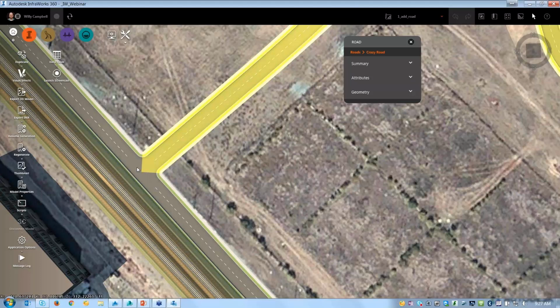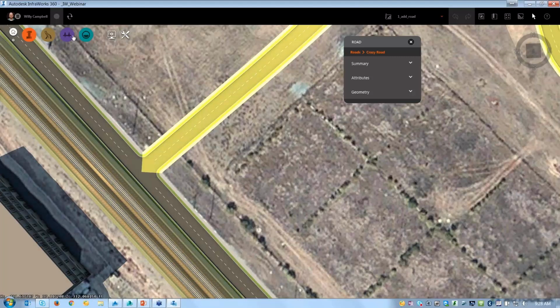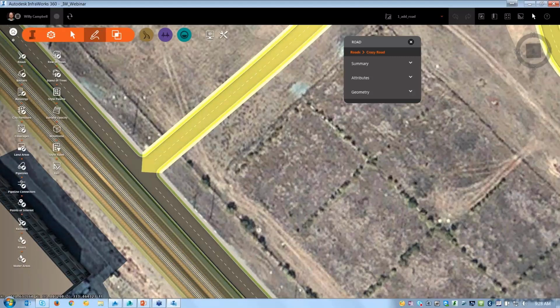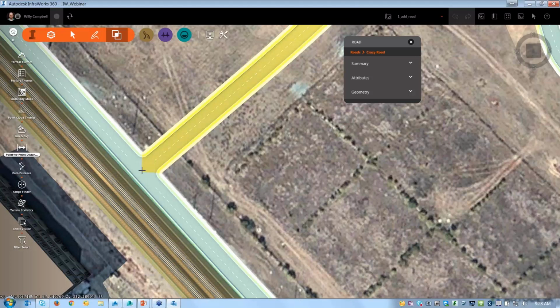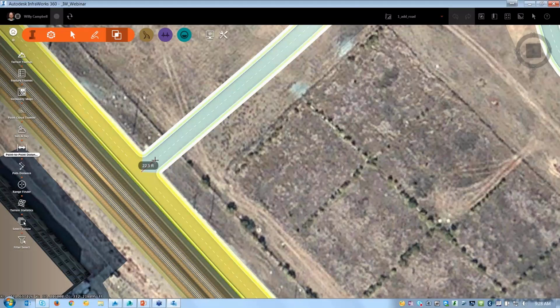So what I actually want to do in Civil 3D before I export my line, and I did manage to forget this step again, but we can do it real quick. Let's see how much distance I need to trim back from this to bring that feature line shorter. So if I come over to Settings and Utilities, oh no, I'm sorry, go to the orange eye and come over to Analyze Your Model, and point-to-point distance, I can measure from the center just about to where those curb returns end. It's about 20 feet that I want to trim back on the west side of the road there.